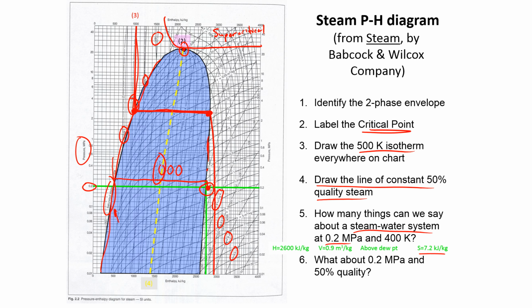And we want to find 7. Let's see if we can find this line. Looks like it's kind of covered up, but it's 7.5, about right there. So it's going to be about 7.2 because it's between 7 and 7.5. That's the entropy, and we're going to use that when we compress, especially for reversible compressors.